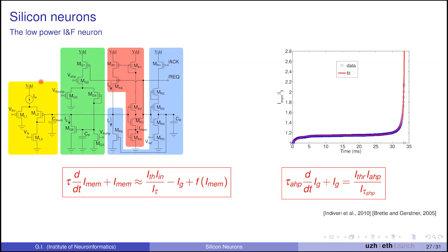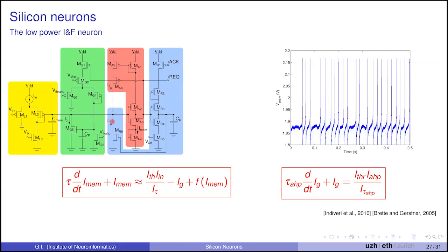Now, if you keep on injecting current into the neuron, you will keep on getting spikes in output. And now you have a two variable system where they interact. It's a physical system. So this is actually a chip that has thermal fluctuations. You have picoamps, so they're comparable to the currents due to thermal fluctuations. And you can see that if you have picoamps in input, you have very low frequencies. This is half a second. And because of this influence from the thermal fluctuations, you have variations in the output. You have variability.